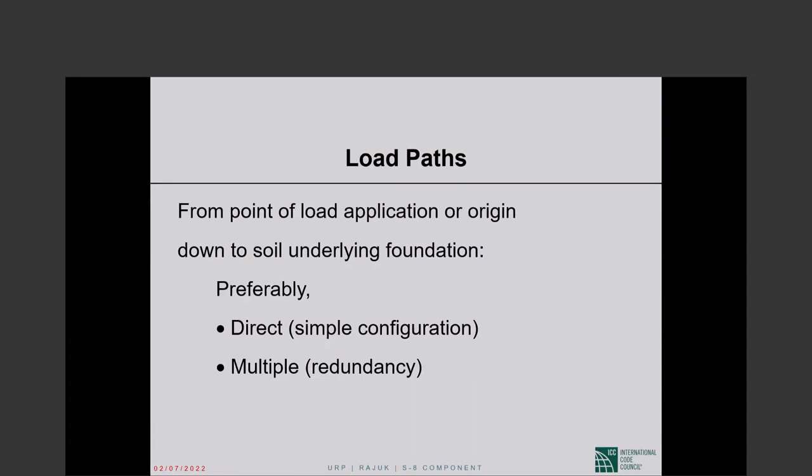It is very, very preferable in seismic design to have direct load paths, which will be provided by simple building configurations. If we have too many setbacks, projections, this and that, then the load paths are complicated, and that is to the detriment of the structure. We also very much like to have multiple load paths rather than just one, and that is the concept of redundancy.